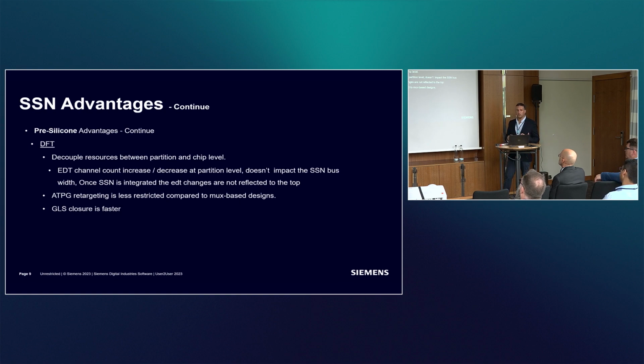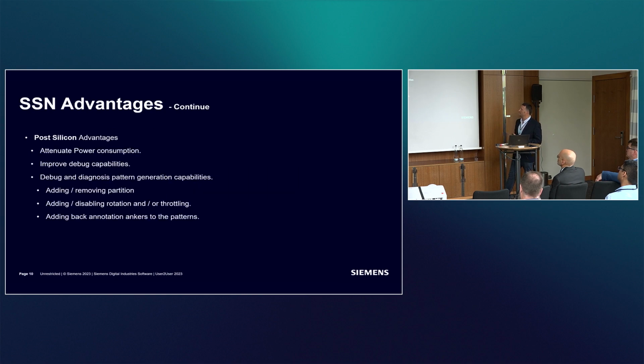You don't need to run the whole content, because usually GLS at top level is a pain in runtime, especially if you're running with SDF. Even if you black box all the other modules, it's going to be complicated. And here we didn't have to do that. It was really easier for us to implement.